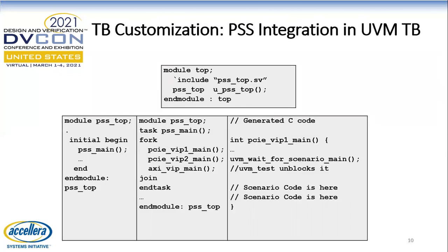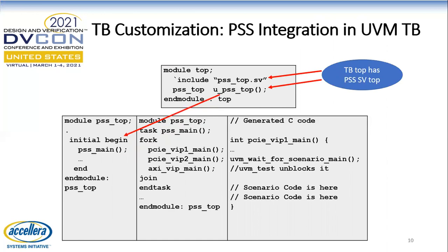Moving to the next slide, Testbench customization. Here, how PSS is integrated to UVM Testbench will be discussed. The top rectangular box is the Testbench top module. PSS SV top is instantiated here. The PSS SV top has initial block. Hence, once the simulation starts, the PSS also starts.